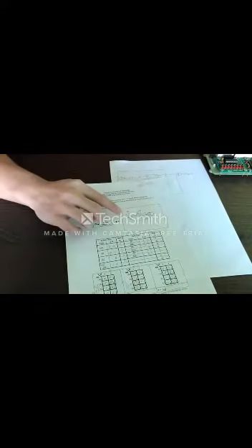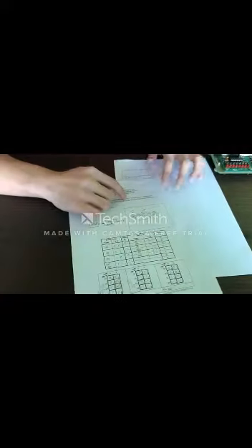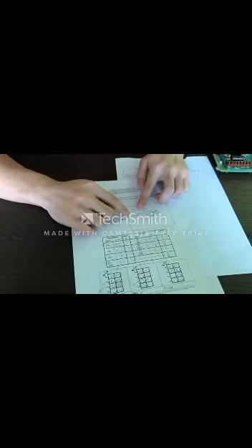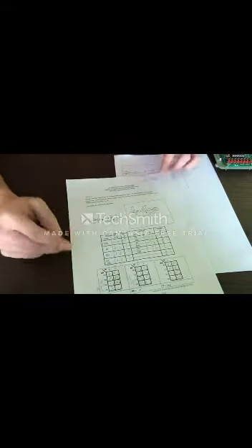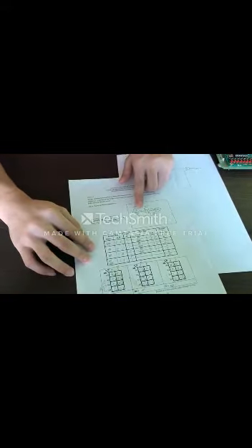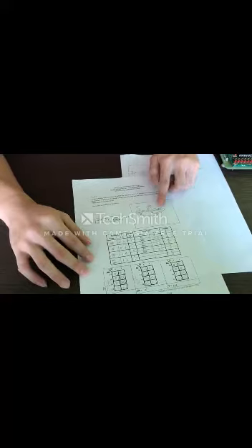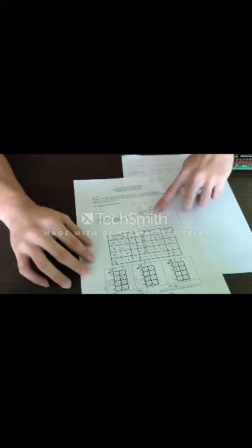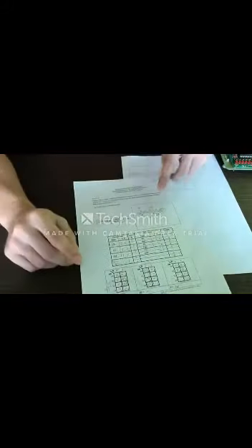When it's idle, the correct output we want is 011, so the first one should be 0. But when the first input is 1, it will loop back to idle, which handles the overlapping sequences. When the correct input 0 arrives, it will move to F0, and then another correct input, which is 1, moves it to F01. But at the second part, when the input is 0, which is the wrong input, it will go back to F0. At F01, when the input is wrong, which is 0, it will move back to F0.